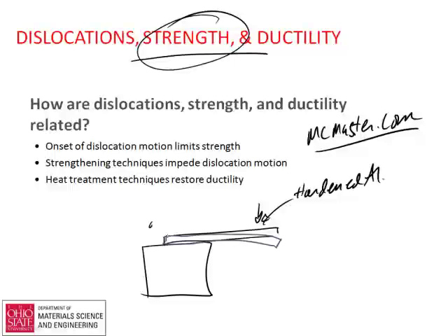Maybe under a 20-gram load, it would go twice as far. And what you could do then is take this material, heat it up with a propane torch, do this again, and you'd see that for the initial deflection where it returns, you'd have the same stiffness, but it takes a much smaller load to put permanent deformation in it.